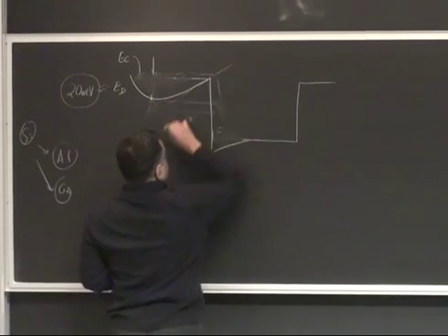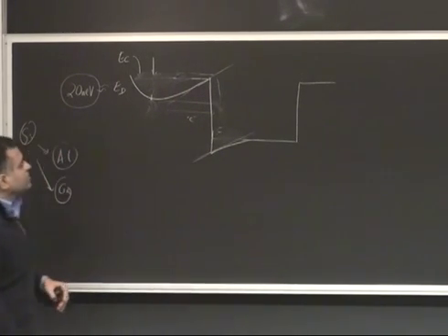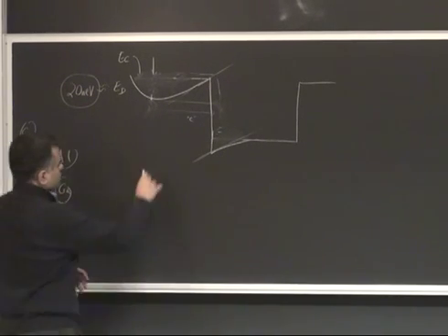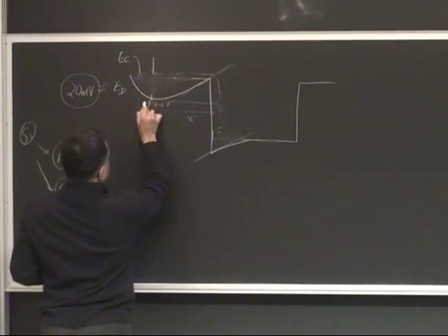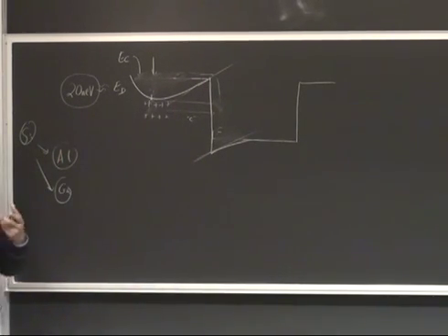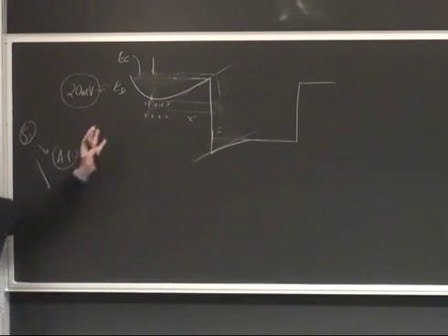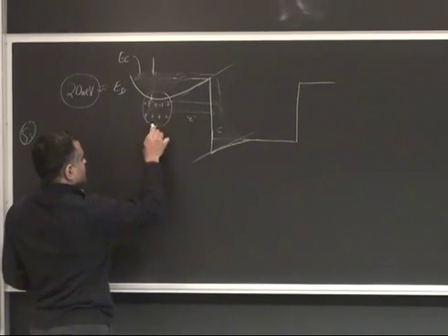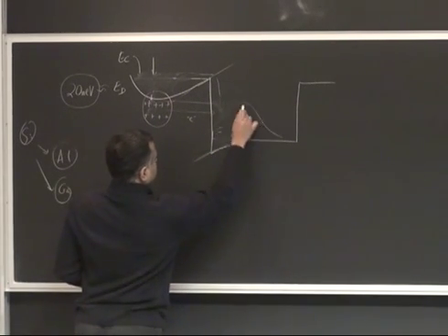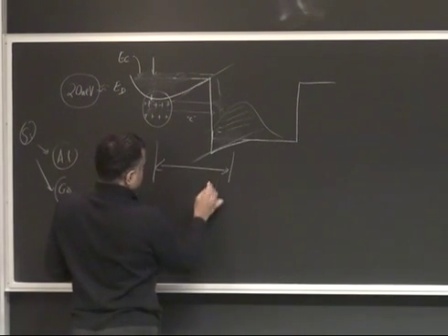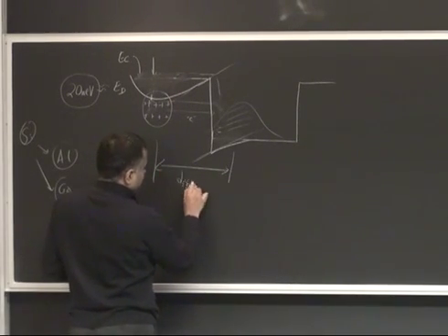Yeah. So the slope here and the slope here for gallium arsenide is going to be the same, but for gallium nitride, we'll see later, would be different. So there's a polarization charge at the junction. Anyway, because we are going to put the positive charges here, this is what is called modulation doping. And also, please read, I posted Herb Kroemer's article where he describes the importance of this property. So you see the ionized donors are sitting here, but the electrons are kind of here in this quantum well, and they're separated physically by this distance, which you can call a spacer layer or something like that.